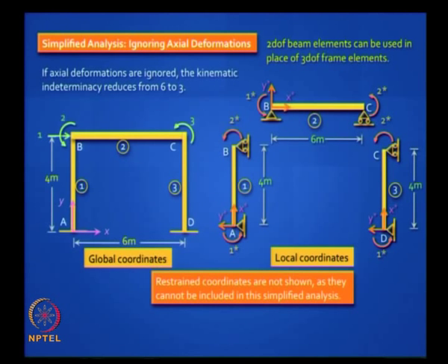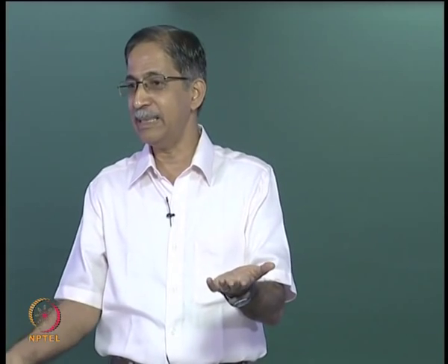The reason is, once you are going for chord rotation way of dealing with sway, then do not bring in those restraint degrees of freedom, which means now how do you deal with the 10 mm support settlement at D? You understand? Now how did you do it in slope deflection method? Let us say that portal frame D goes down by 10 mm. Earlier you could handle it because in the dr vector you could fit it in. Now what do?